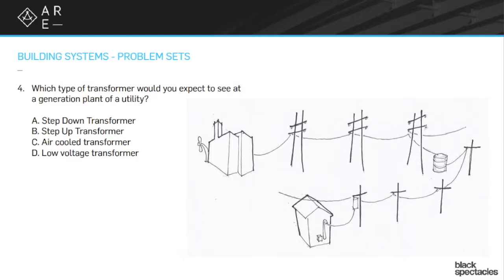And then as it gets distributed around through what we would think of as telephone poles or underground systems, it'll get to the actual use point. So say, for example, a little house with the little transformer up on the pole out in back of the house. That's a transformer. That's where it's stepping down from the distribution level of power to the actual use level of power, the everyday use that we would normally find, either the 120, 240, that kind of range.